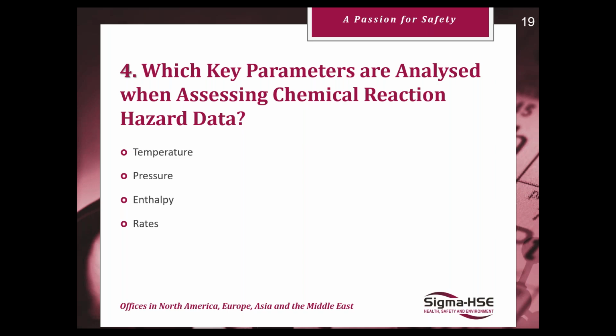So we may do an isothermal assessment for reaction calorimetry, but also for assessing thermal stability. We may have a need for heating up a material to a certain temperature and holding it for 12 hours, for example, to assess whether it's going to start to trigger a decomposition over that sort of time frame.